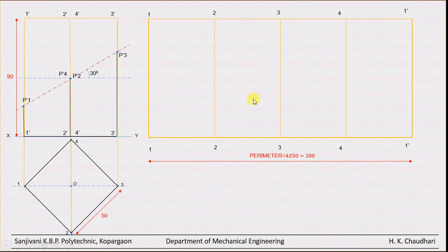So these two edges represent this point or this edge. Clear? Now to locate the remaining points, just draw the projections for locating this point. Draw the projection from this front view, or directly you can take a distance of this vertical distance from P-1 to 1 dash in compass and directly mark here, but we have to show the procedure.